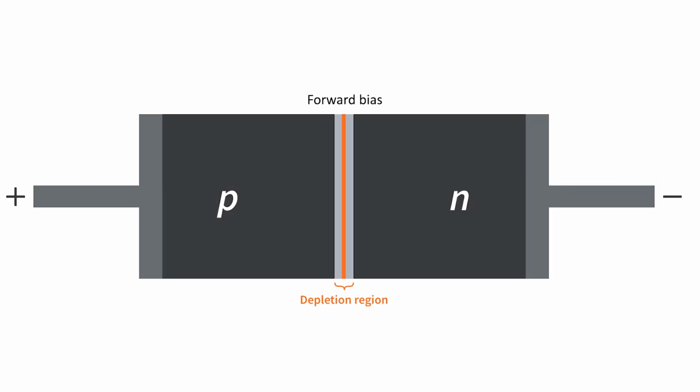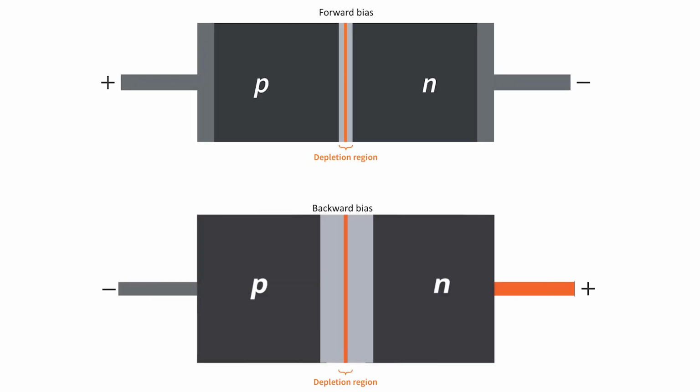Forward bias, meaning the voltage potential is connected positive plus V to the p-type material and negative minus V to the n-type material across the diode, which has the effect of decreasing the p-n junction width. Forward bias means that it allows the current to flow through the diode, and reverse bias means that it blocks the current flow through the diode.